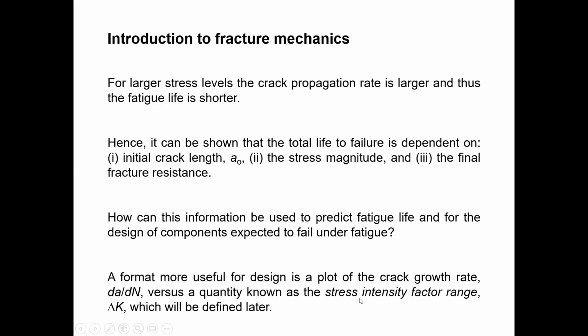The fatigue stress concentration factor is Kf, but the stress intensity factor we normally call K, or if it is a range, delta K. I hope you understand the difference between Kf and this K value. Again, this is not the fatigue stress concentration factor. It is a different term, the stress intensity factor.